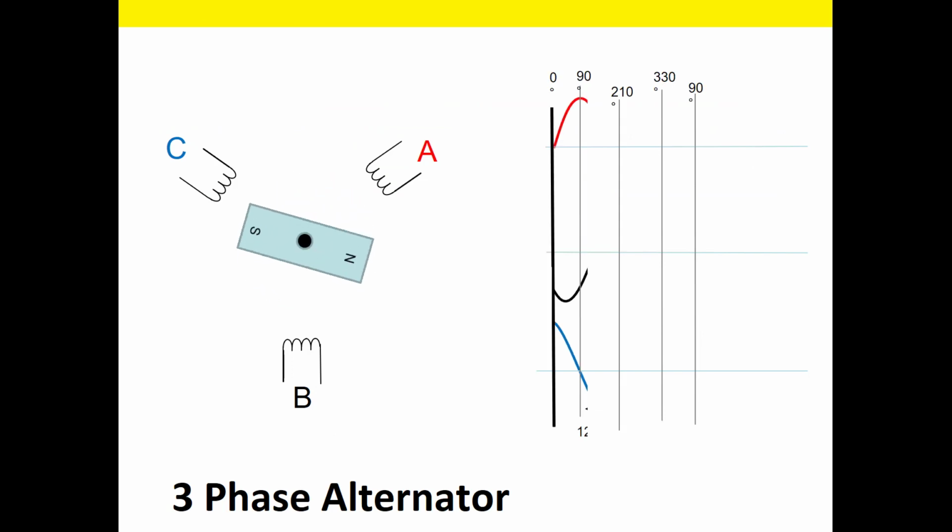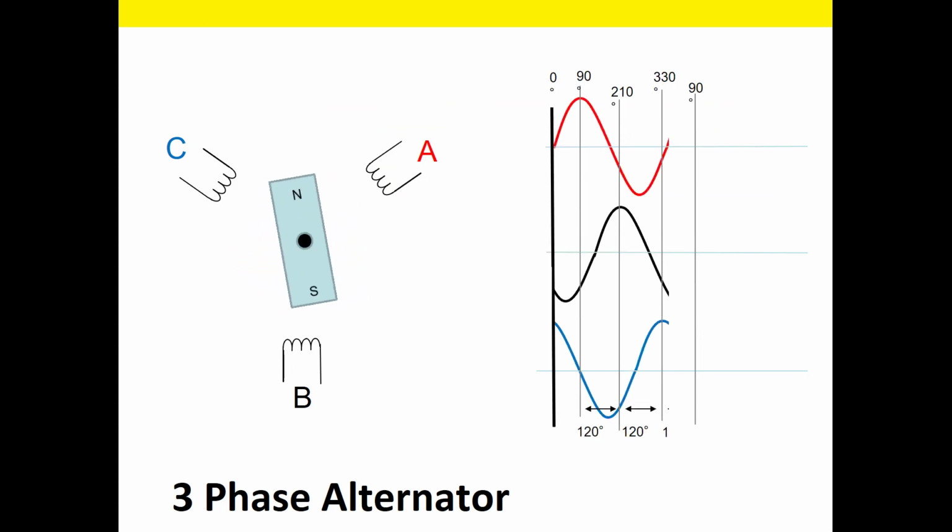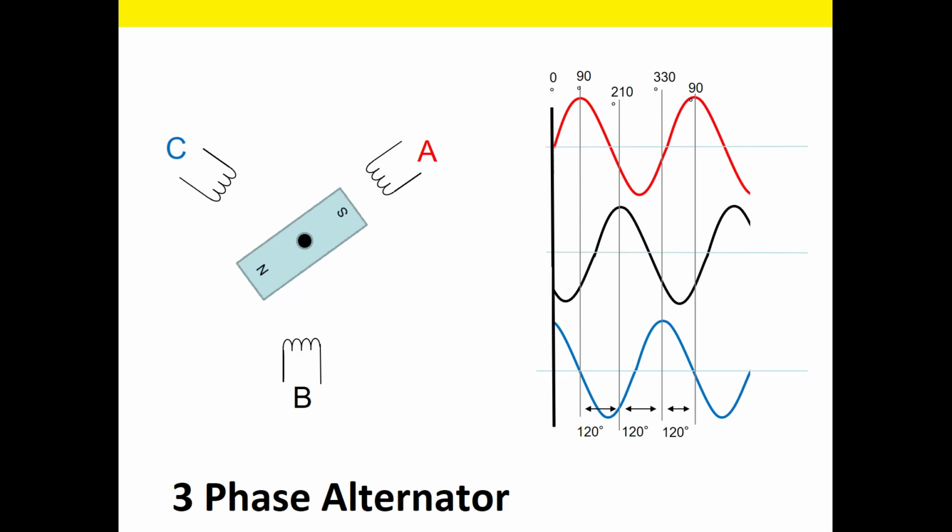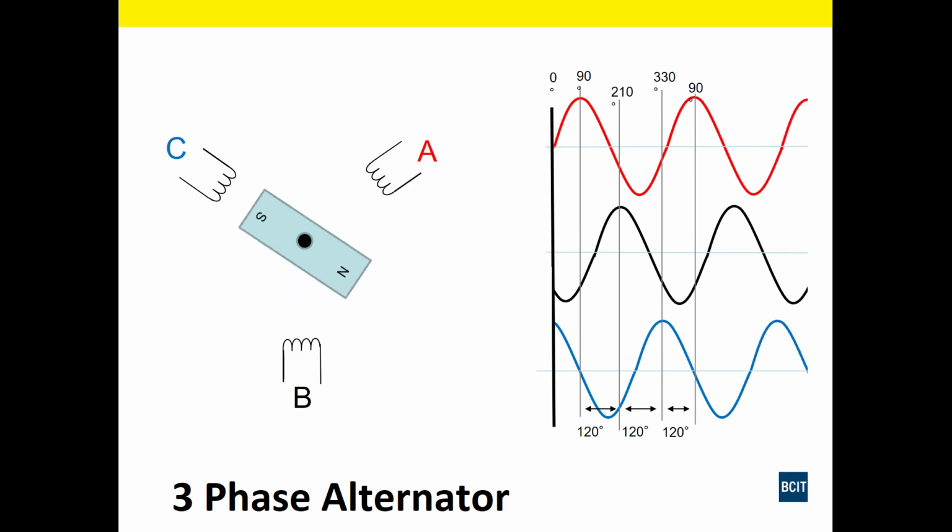Okay, as you can see here, to generate three-phase AC, we need a rotating fixed north and south pole in our field poles, our rotating field. So to achieve that, we have to use DC in our field windings for our rotating field poles.